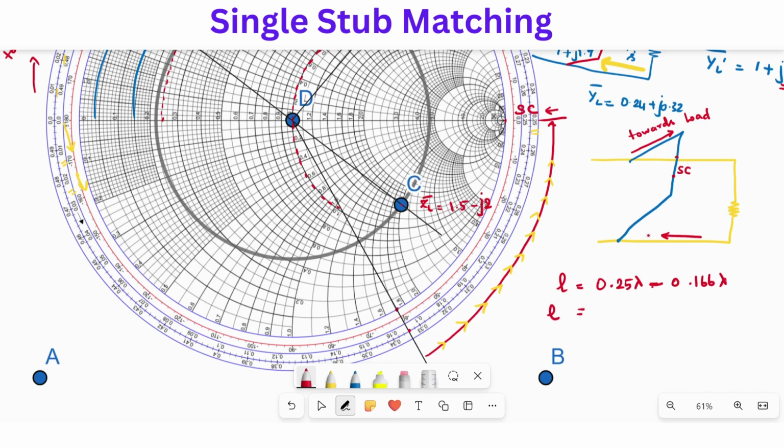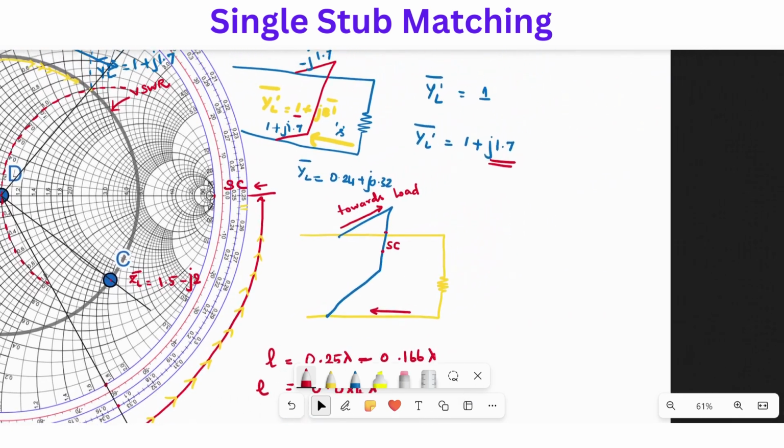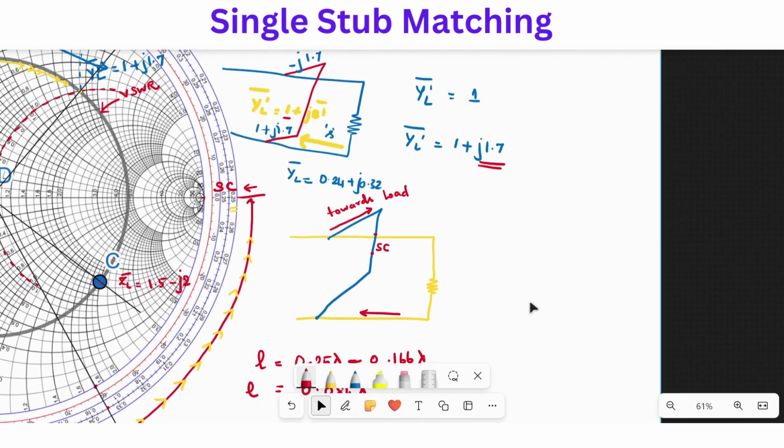Let me calculate it. 0.25 minus 0.166, which is 0.084 lambda. That is the length of the stub, which will provide a reactance of minus J 1.7 that will be cancelled out when we consider the load point. So our load will be YL bar equal to 1, so impedance will be matched. So we have measured two values as of now.